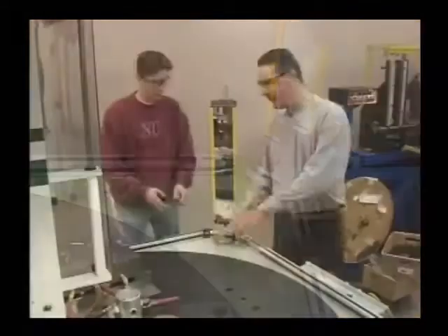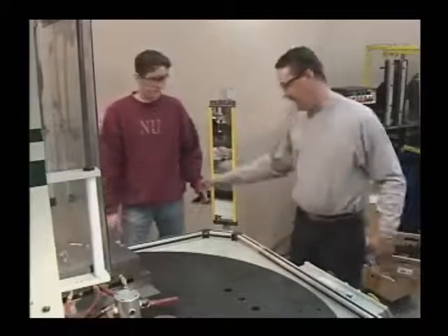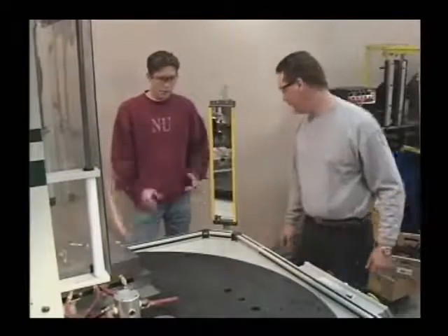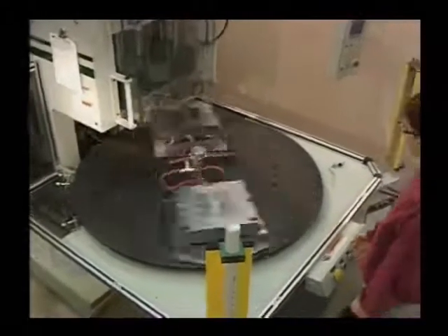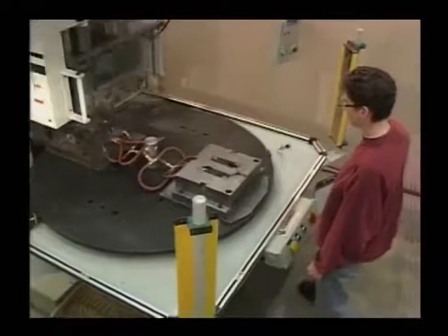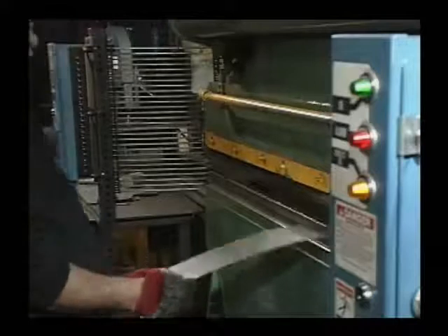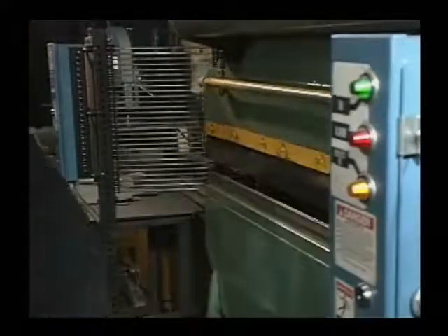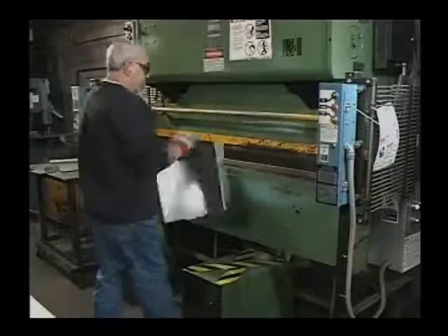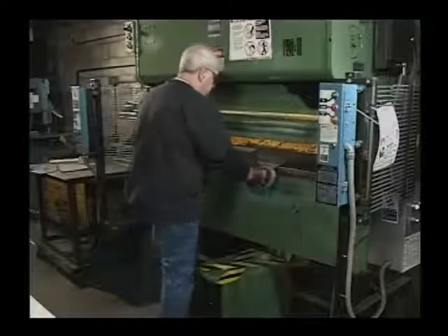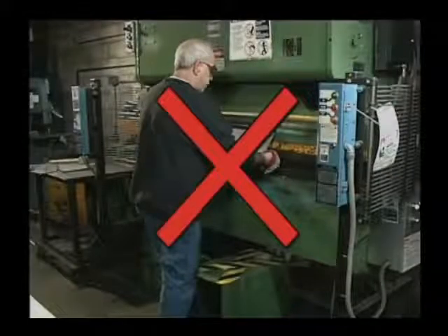By reflecting the beams of light onto a series of mirrors, a curtain of protection can be created around the machine's perimeter. This keeps workers from getting close to the hazards associated with any part of the machine while allowing for a clear view of all operations. When used at points of operation, light curtains are often set up so that raw materials being fed into the machine will not trigger a shutdown. But if the light curtains permit a finger, an arm or any other part to pass through without shutting down, the machine is not set up properly and must be readjusted before someone gets hurt.